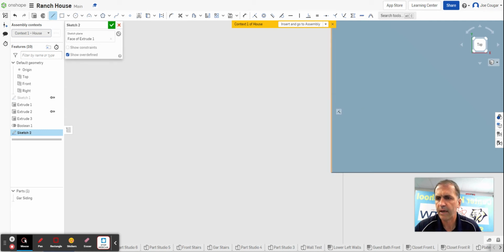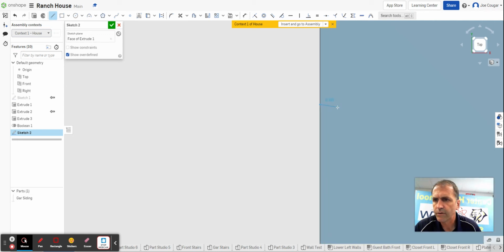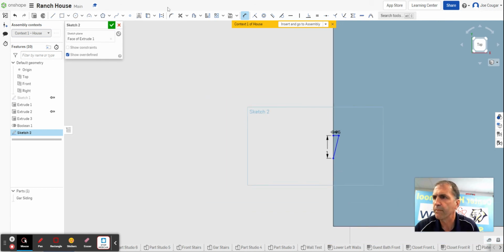Okay, we're going to make a right triangle that goes out 1/4 of an inch, 0.5, and then down till you hit that. And then we use the dimension tool, as we've done before, to dimension this to this as an inch. Okay, and finally, from the bottom, we're going to dimension from the bottom to this.